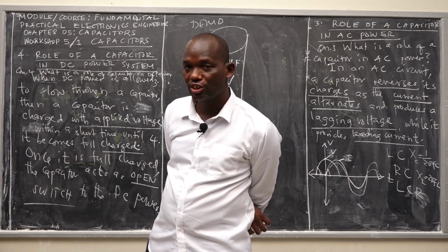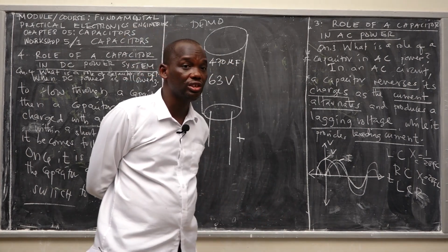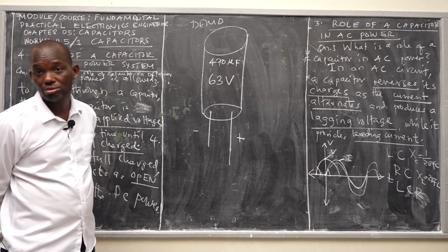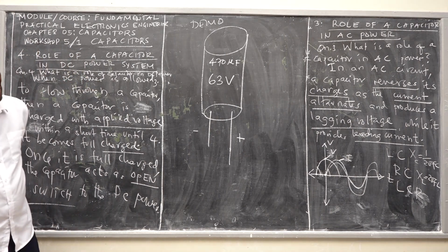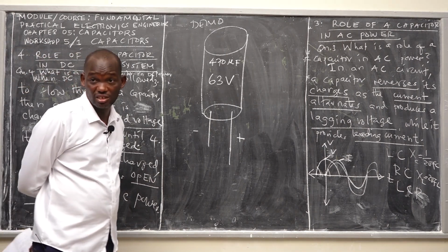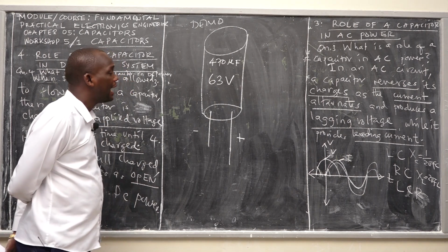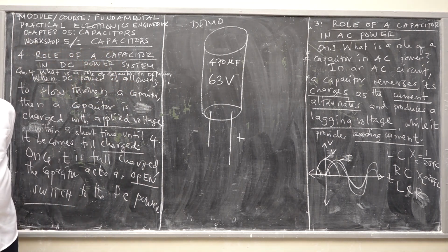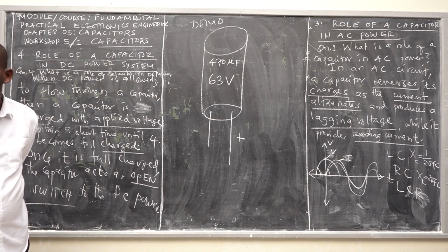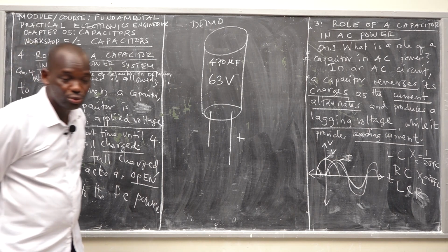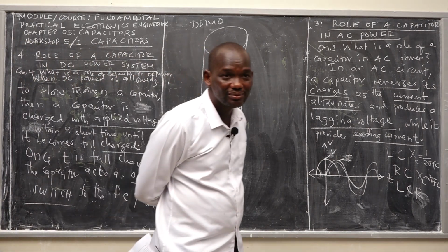You know the maximum voltage is what? 12 volts times root 2, which gives 16.96 volt, right? And then we have a potential drop of 1.4 volt in the bridge circuit. Do you remember that? So you usually remain with, let's say, 15 volt.